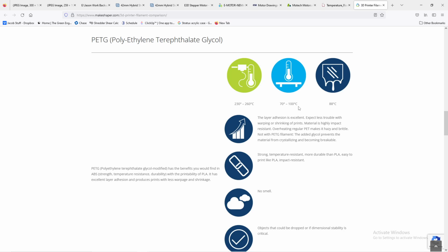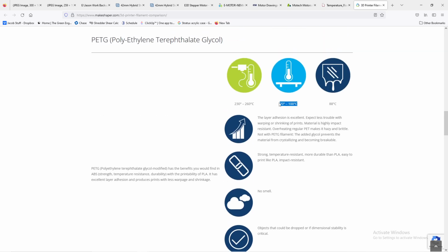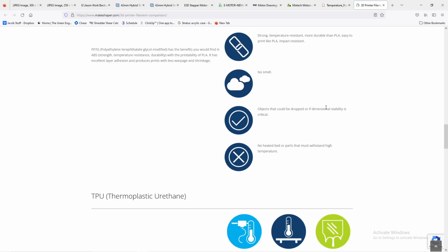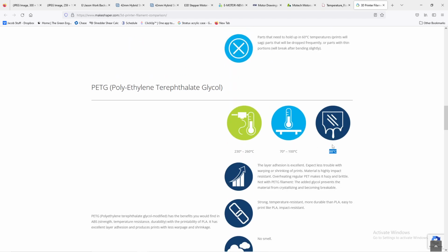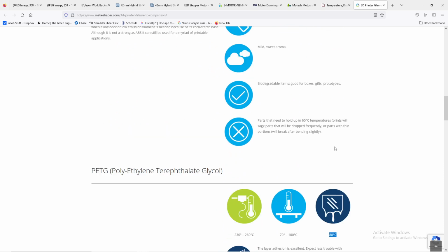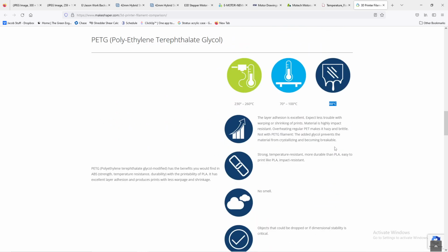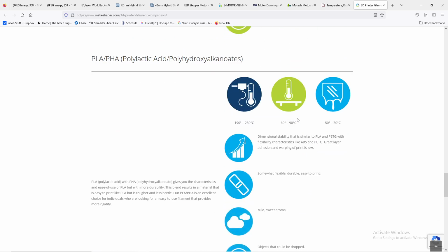part will cool down, right? The bottom will just maybe be at that temperature, but the environment is sucking the heat out of it, right? So you might have to mess with this a little bit and see where the temperature of your enclosure gets. But generally you don't want to have the bed exceed the glass transition temperature, just in case you don't want that bottom layer to start to get weird and come undone from the bed, right? You can see here TPU, it says like below room temperature, but still 40 to 60C. It doesn't really matter, you're past the room temperature anyways.